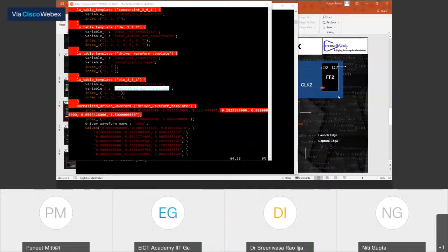So I think this question, a lot of people are asking: setup and hold time are decided by the flip-flop parameters, which decide the delay of the flip-flop. So these values are dotted with respect to the related pin. Yes, good. The significance of negative hold time and setup time, Venkata, I just mentioned, I'm going to discuss that later on. Now, how will positive and negative edge trigger flip-flops affect the setup and hold violation?